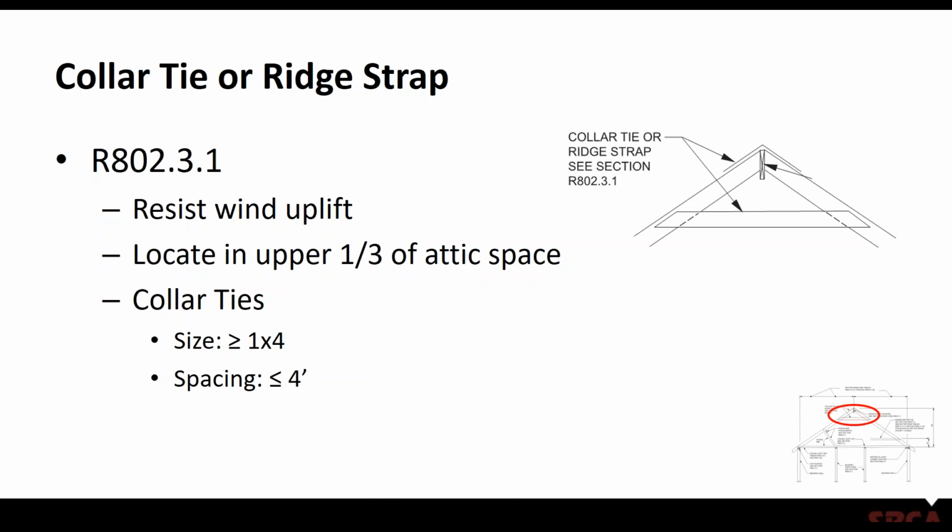Those of you that have been in the truss industry long enough know that about 20 years ago, it wasn't that uncommon to see 1x4s specified for lateral restraint or even web reinforcement. The problem with trying to use a 1x4 today, again, is they're not graded for structural applications. They're graded for architectural, and so it's very difficult, unless it's regraded, to put design properties on that product.